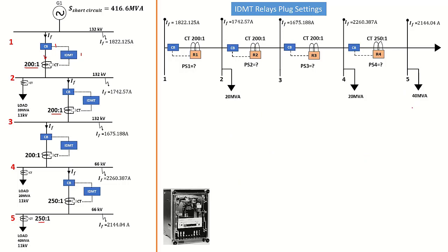So now we're going to work from the lower relays to the upstream relays. That way, the relay at the bottom, which is relay number 4 here, will be looking out for the fault that is going to be available on busbar 5, and relay 3 is going to be looking out for a fault on busbar 4 and busbar 5. Relay 2 will look out for the fault on busbar 3, busbar 4 and 5 and so forth. So this is why it's better to lay them out like this, and then you can see clearly.